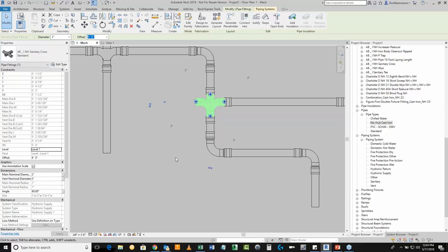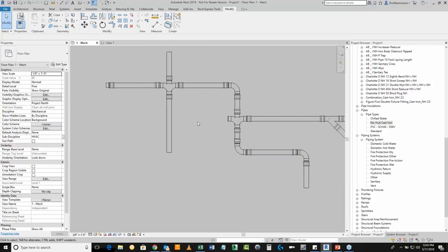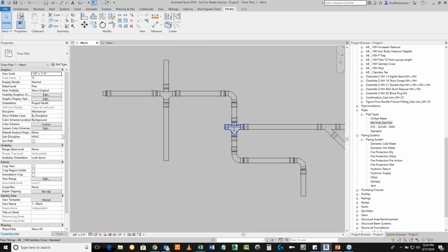Yeah, and just getting another piece of information in here from one of the viewers of the webinar. Thank you very much. You create a sanitary pipe system with P-traps defined as elbow fittings. That's a great idea, even if it's just a single routing preference that is set up partially. I really do encourage you guys to take advantage of the fact that it doesn't matter where you get these fittings from, if you made them or you get them from a downloaded manufacturer, you rip them out of somebody else's project, it doesn't matter.